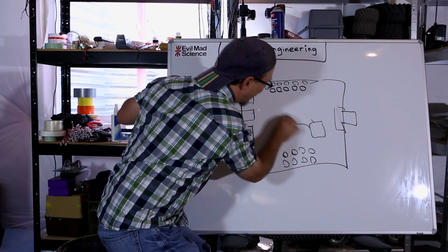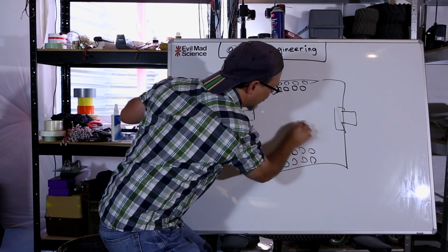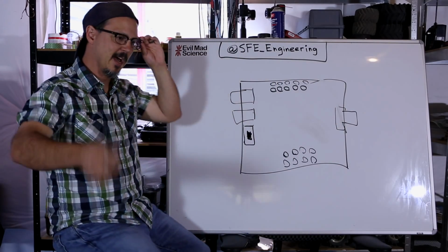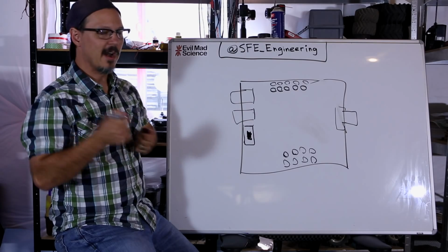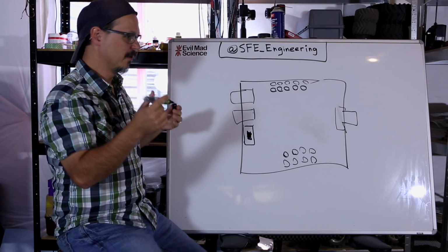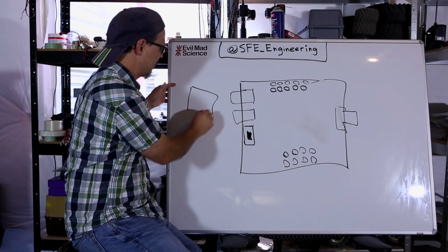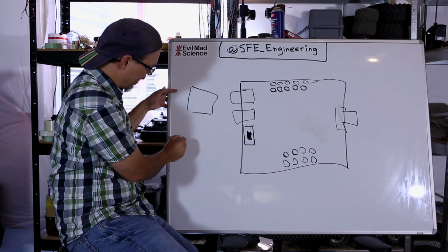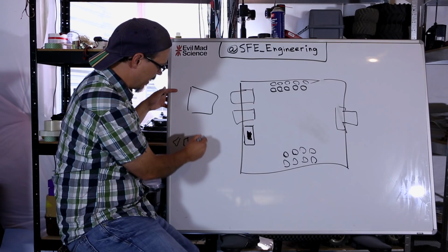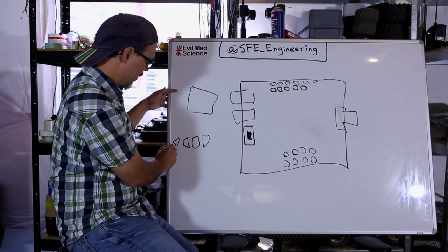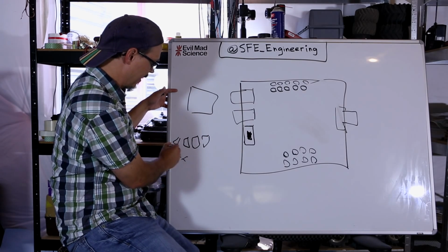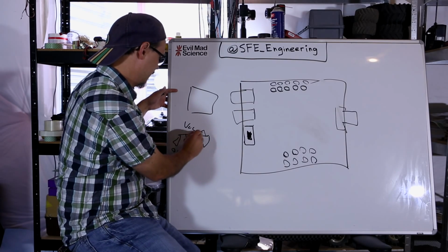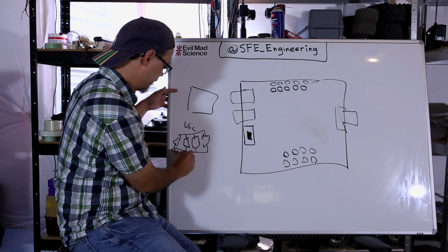board. And in fact, while I'm on the subject of microcontrollers, another mistake that I have seen many, many times, thankfully not by our guys anymore, is that on any schematic you will see a microcontroller as some piece, and then you will see a bank of caps, and this is the schematic, right? They'll all be 0.1 microfarad, and they're all tied to VCC, and they're all tied to ground, right?